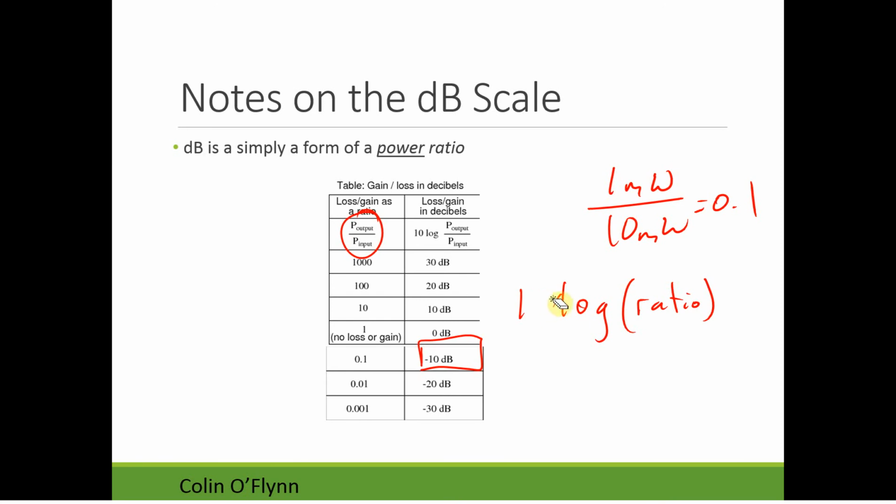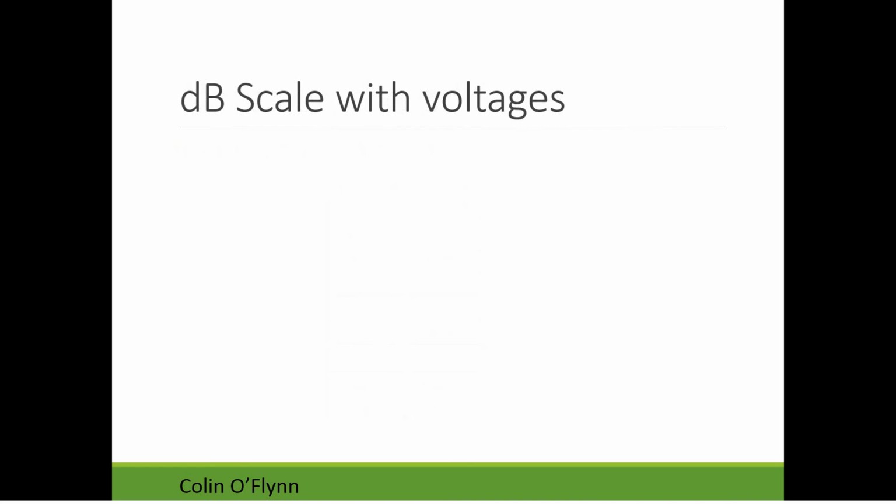This is solely for power. It's important to note, as you'll see decibels throughout everything you do, and it's important to realize it's always talking about power ratios. If you're using voltages, this is the trick.